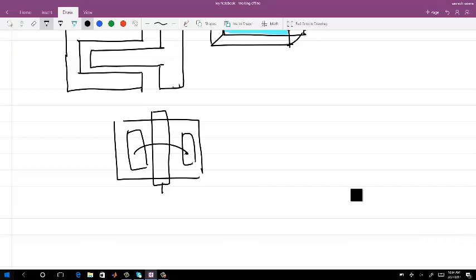Now on top of this MOS, where all the connections are limited to M1, you can place this fringe capacitance on top of it. Okay, and then you can have M2, M3, M4, M5 till whatever metal you want to use. So if you go from M2 to M7 or something, you can increase the density by 50%. Normally for MOS capacitors, the density turns out to be, at 1 volt, something like 10 or 11 femtofarad per micrometer square. But you can increase that to like 17 femtofarad per micrometer square if you can do that.